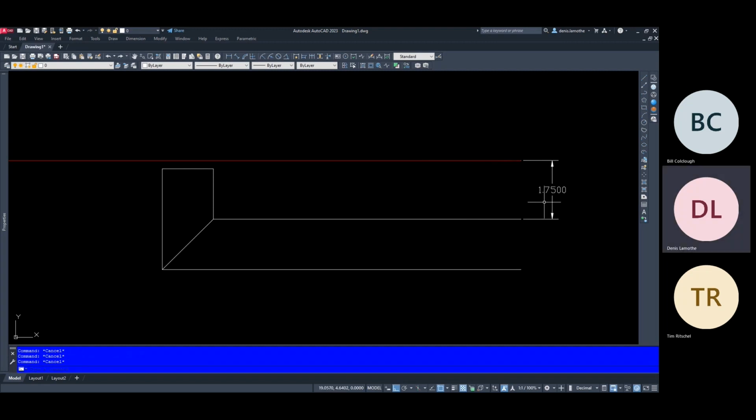Having said that, on occasion we come across a situation where we're using handrail brackets that we may order from a vendor. They're prefab, pre-made, and designed a specific length and offset from, say, if it's a glass applied handrail bracket. The design will have been made so that it is exactly 1.5 inches. So if we're using a bracket from a vendor instead of something that we are fabricating ourselves, then that 1.75 inches may have to revert back to the default 1.5 inches. That would be the only time I think I would be forced to use 1.5 inches.